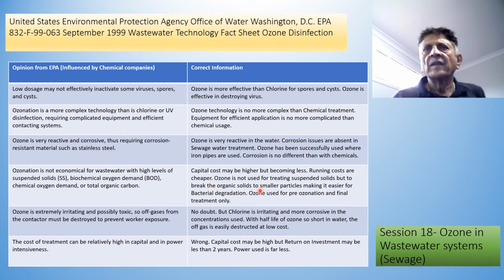material. And further, in wastewater, we use pre-ozonation to break down protein material, and that will save the digestion time by more than 50%. Therefore, ozone is much more economical because there's a saving of time factor. In cities where the land prices are expensive, you have to use less tanks, and instead of allowing 5 days for complete treatment of the sewage system, we need only 2.5 days. That is obviously much better and saves a hell of a lot of money.